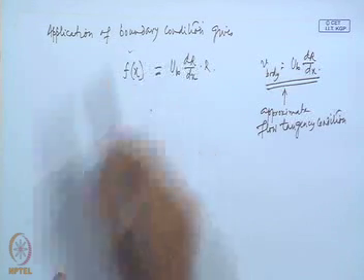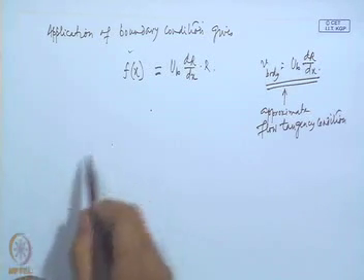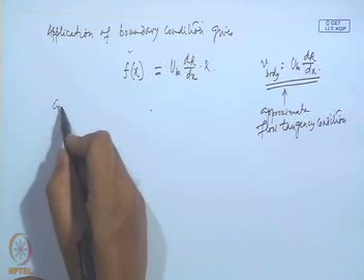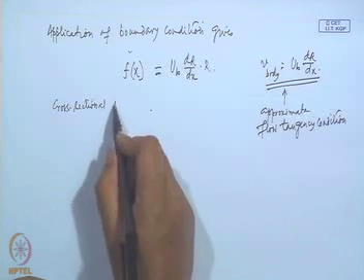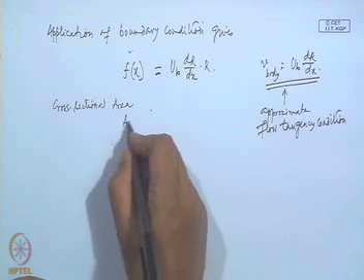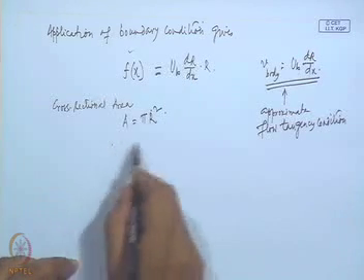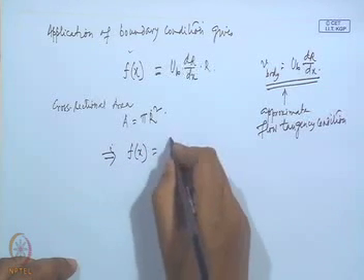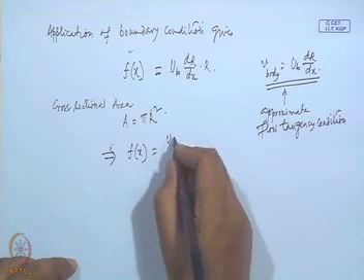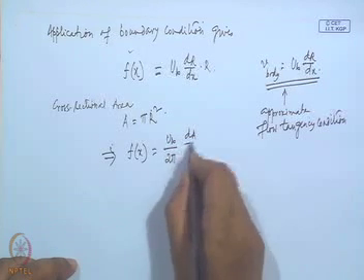So, this gives the distribution of source strength for any arbitrary profile, and assuming that the cross sectional area A is pi R square, introducing this, f x is u infinity by 2 pi dA dx.